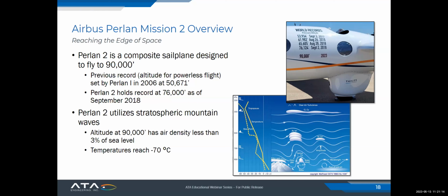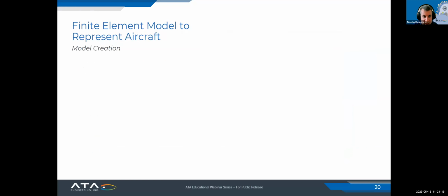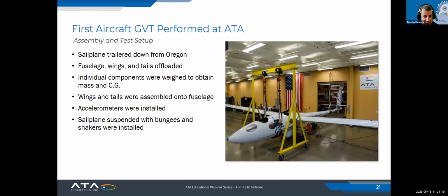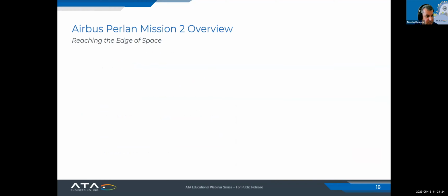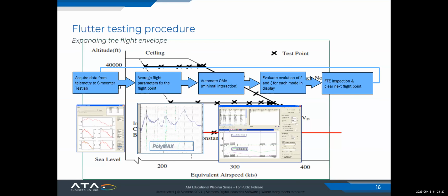The flight. Yeah. So the flight testing is definitely some of a, let's see, this was probably the best slide to show it. There's a little bit of art to it, but basically when you're flying, you're trying to excite a particular mode or set of modes. So with the stepper motors, you'll try and drive it at the frequency of that mode, because ideally you want to drive energy just to that one mode as best as possible.